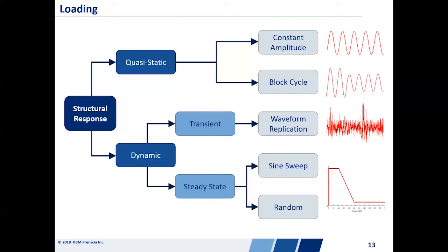Now, these are simplified representations of cyclic loads in the time domain. They are going to have some sort of equivalence to damage based on a real-world event. But the frequency of those cycles is really not going to have any impact on the response or the damage that that part would see.